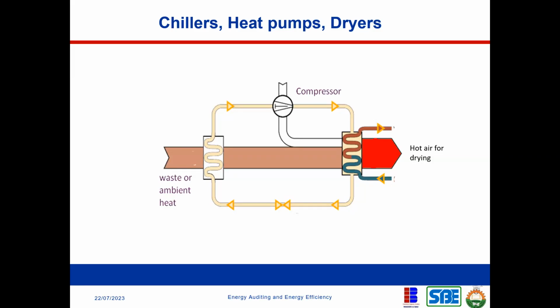Now, what a heat pump does is that it compresses atmospheric air. Now, when you compress air, if you compress air, you reduce the volume of the air. What you actually do, you increase the pressure and you increase the temperature. That's what happens. When you compress air, you increase the temperature. So when the temperature is elevated, you can use air to collect the heat from the compressor and dump it into water.